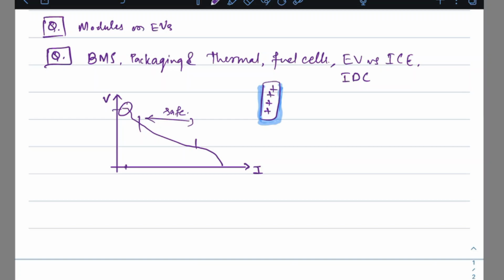Borrowing from a smartphone example, what they do now is split the battery into two different cells so that you can charge them in parallel, right? Charging in parallel allows you to push in more energy or more current from your charger, and that's how we are looking at 120 watts and almost 200 watts in phones. So charging batteries in parallel is one way to go about it.